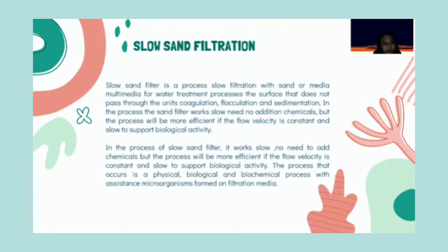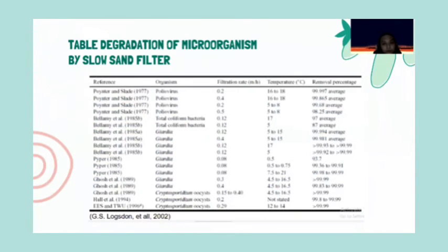The slow sand filter works slowly, with no need to add chemicals. The process that occurs is a physical, biological, and biochemical process with the assistance of microorganisms formed on the filtration media. And this is the table of degradation of microorganisms by slow sand filter.